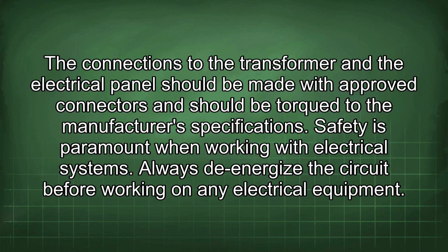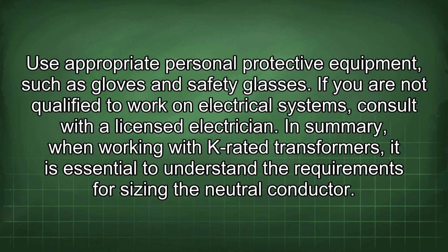Always de-energize the circuit before working on any electrical equipment. Use appropriate personal protective equipment, such as gloves and safety glasses. If you are not qualified to work on electrical systems, consult with a licensed electrician.